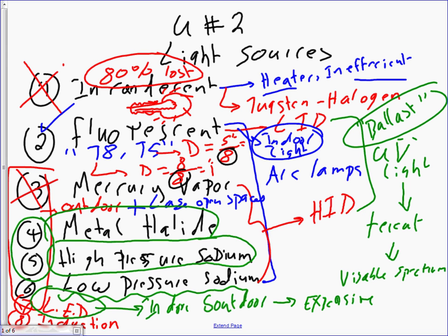Then we move into another arc, metal halide and high pressure sodium. Right now, everybody knows why I crossed the mercury out here, because of environmental reasons. Fluorescent light is your fixture of choice after LED now, if you're doing a commercial building, like you guys have done with me, right? So that's why I get the check here. Then moving into, what if you're doing a parking lot or manufacturing floor? You have 2 options, metal halide or high pressure sodium. Both of these, the only difference is the chemicals that they use inside them, guys, to get you the light.